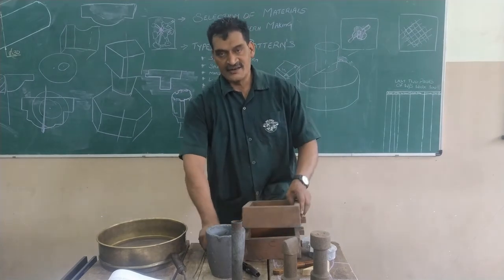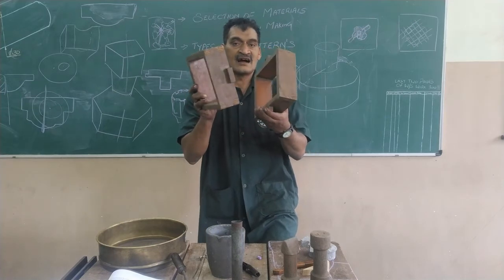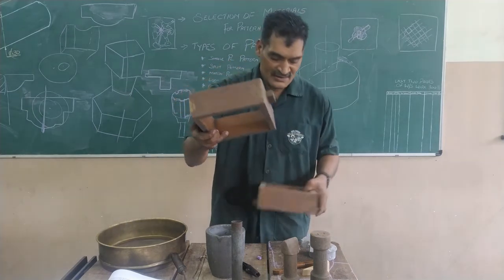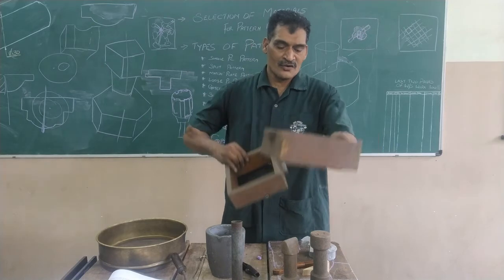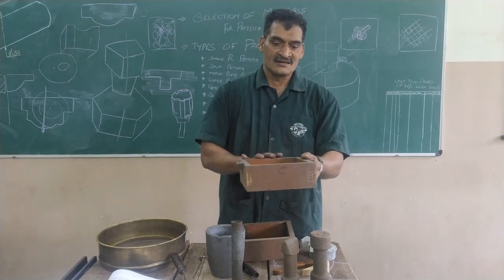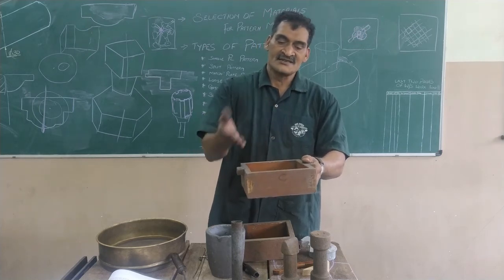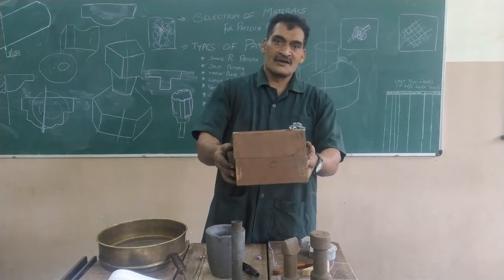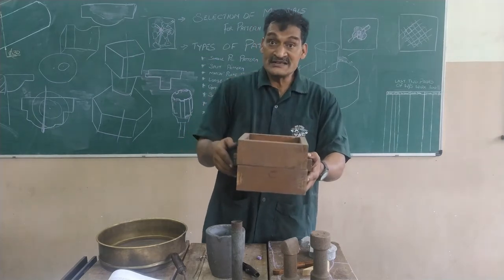After the so-called drag pipe, we have flasks. These are the molding flasks that are used for preparing the mold, in which there will be two flasks. The lower flask, which is kept at the bottom, we call the drag. We fill this with sand. After filling it with sand, the pattern is in the center. Then we put on the cope on the drag. The top flask is called the cope, and we lock it with dowel pins.